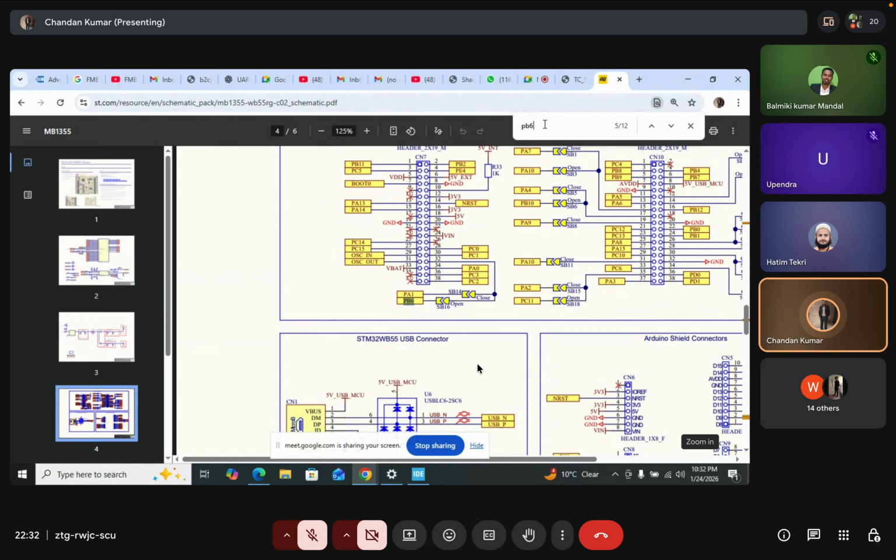He will read the datasheet and schematic and tell you that he is going to use UART on PB6 and PB7, and ask you to confirm from your CubeIDE whether you will be fine with it or he needs to change it. With collaboration of both software and hardware engineers, these custom boards are made.